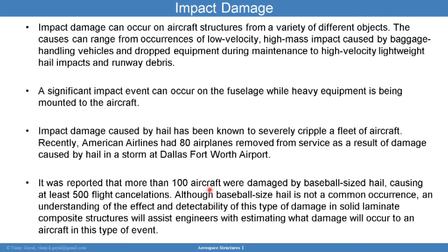And it has been reported that more than 100 aircraft were damaged by baseball-sized hail, causing over 500 flight cancellations. A lot of money was spent trying to fix and repair these airplanes. Although baseball-sized hail is not a common occurrence, an understanding of the effect and detectability of this type of damage in solid laminates can help engineers determine what course of action to take to address these damage events.